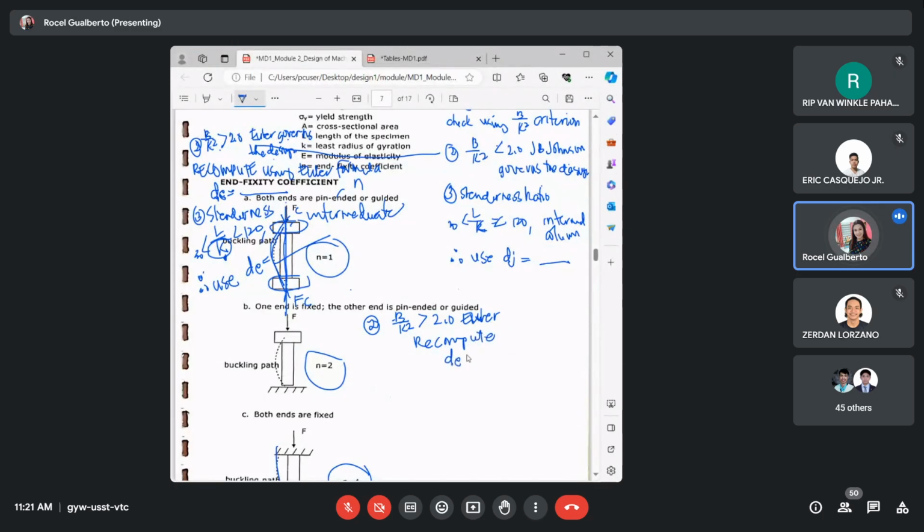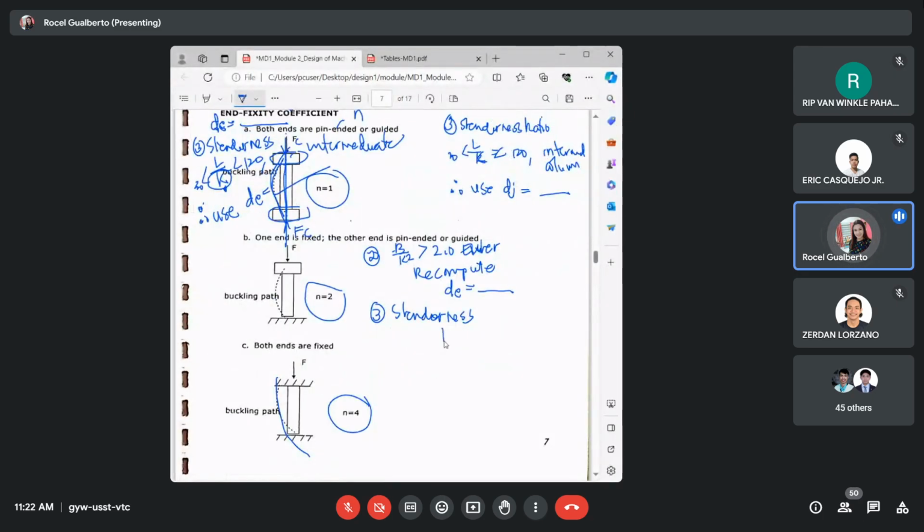May diameter ka using the Euler. Okay? So, may sagot ka na. Anong sunod mo doon? I-check mo yung sa Euler. You use slenderness. Okay? Ngayon, nung i-check mo to sa slenderness, L over K, dito sa K natin, anong isa-substitute natin? Itong diameter po na ito. Halimbawa, ang na-compute mo naging less than 30. Hindi pumasok doon sa in between 30 and 120.